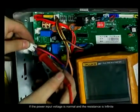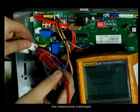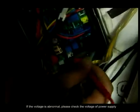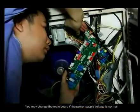If the power input voltage is normal and the resistance is infinite, that means the pump is damaged. If the voltage is abnormal, please check the voltage of power supply. You may change the main board if the power supply voltage is normal.